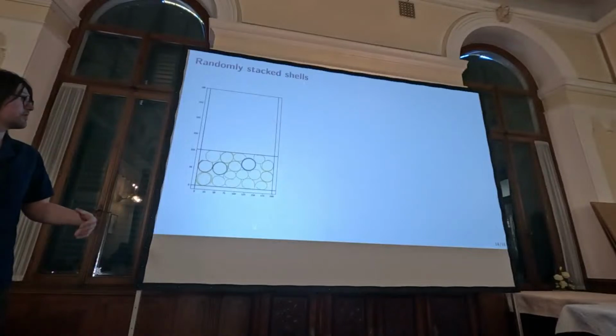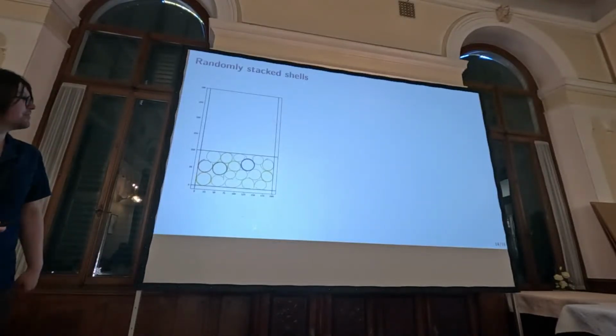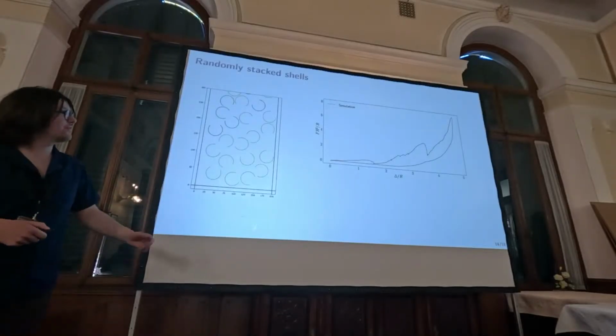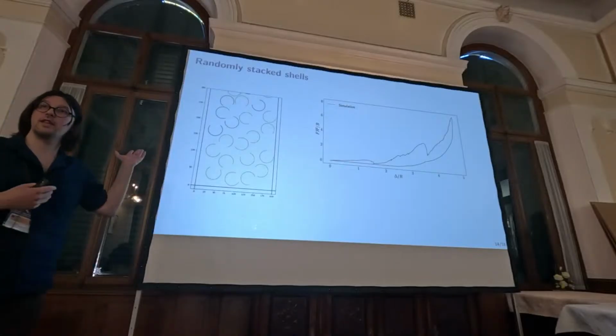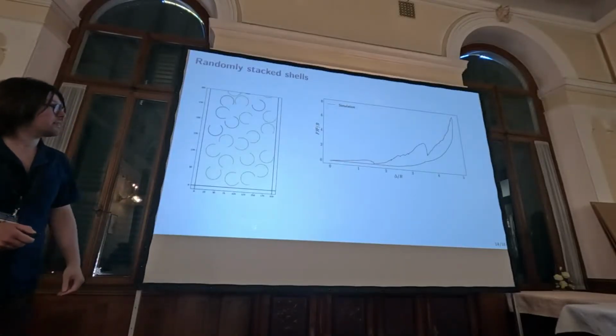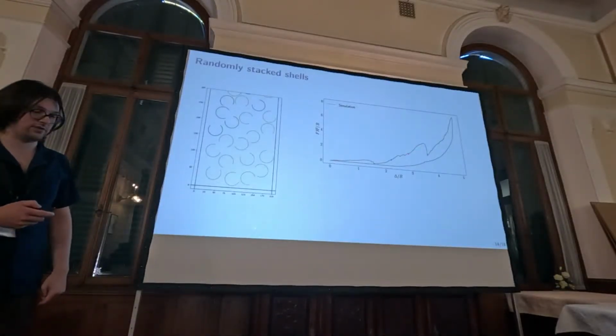And so then we reach a critical load, and we can start unloading again. Unfortunately, I cannot move on; if I move to the next one, we won't see the rest of the video. But to move on, we obtain again the force displacement curve using the equivalent 2D rod model and high-order contact detection method. And we see a similar effect of sudden jumps when snap fit events occur.